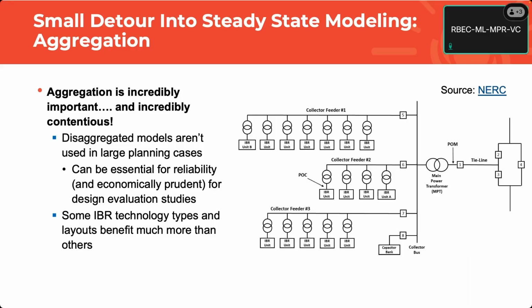The second thing is, this idea of partial tripping is real. But when we're moving to grid studies, if you're thinking about IEEE 2800 compliance and all that, partial tripping is important. It's talked about. But because of these practical constraints, we can put that on the back burner and say we're really interested in a lot of tripping. A little bit of tripping is important, technically a violation, all of that stuff. If you're really interested in it, go and do a special study on it, but focus on the big picture for now. That's my opinion.